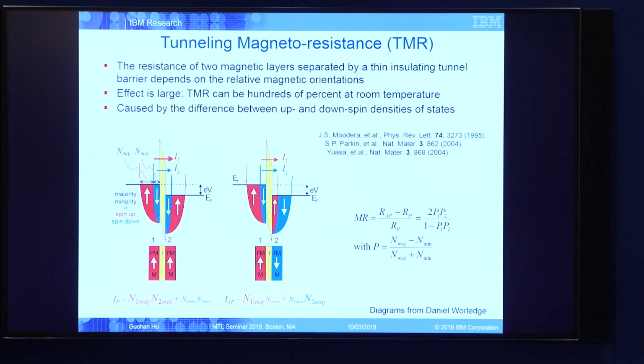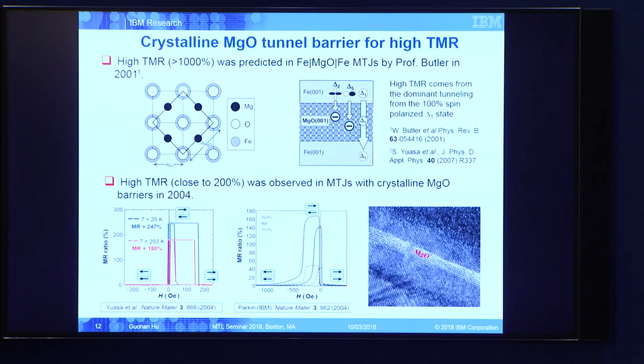So these numbers are okay. For a typical ferromagnetic metal, for example cobalt, nickel, and iron, the spin polarization itself is somewhere around 0.6, 0.7. So it gives you a TMR of about 50%, even for the intrinsic. And once you have some interface defects, the MR is even lower. So this is what we were facing for many years, but people were still trying to make some product out of it, even with the TMR fairly low, 30, 40%.